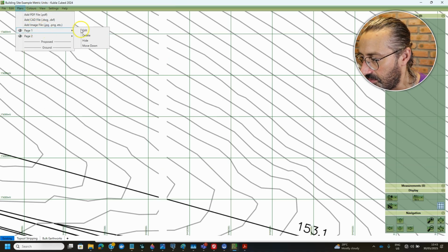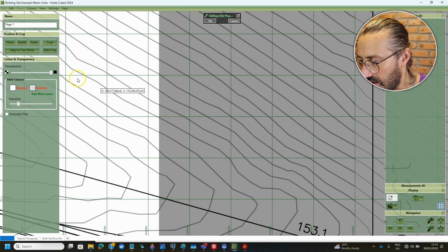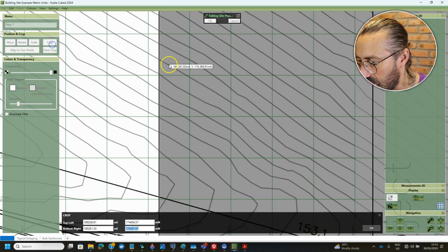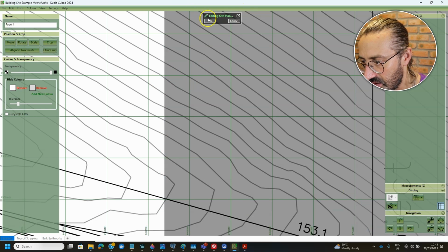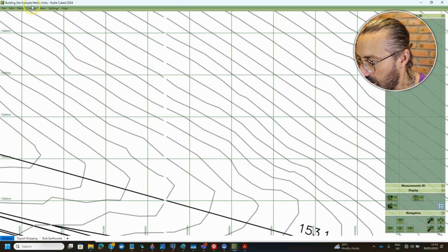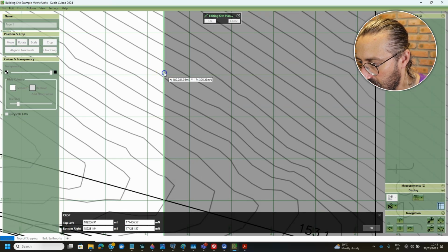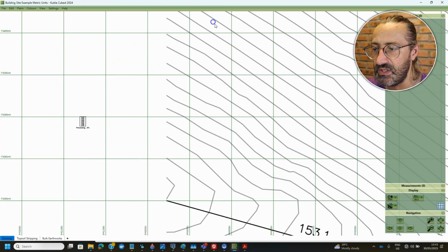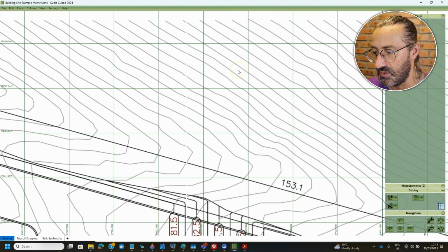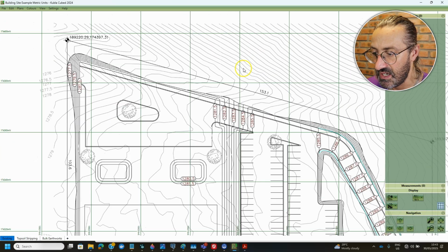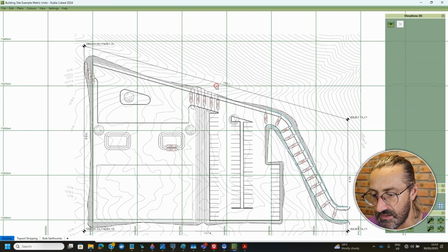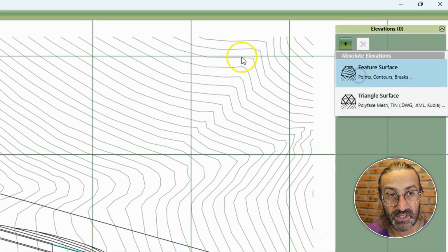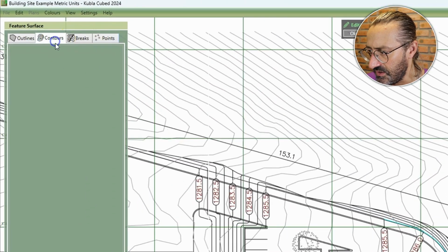I'm going to edit this one again, move it over, crop, and see what that looks like. It probably could be adjusted a tiny bit more. There we go. When we do the extraction now, and we'll go through how to do that with multiple pages, you want it ideally so that when you zoom out, you can barely notice that there's a gap there. So we'll do an extraction, click on contours.